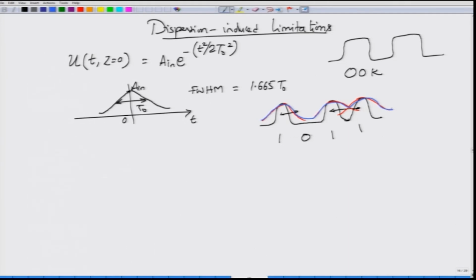This is also getting influenced because if you, for example, have a threshold somewhere here, then you can see that because of the pulse spreading from the previous slot and the pulse spreading from the next slot, the overall amplitude is increased when the bit is 0. So, sometimes if this pulse envelope reaches above the threshold, then even this bit will be in error. In fact, you normally define or model the intersymbol interference by a certain memory length, indicating that the previous m slots to the next m slots are the ones which are interfering in the present slot.